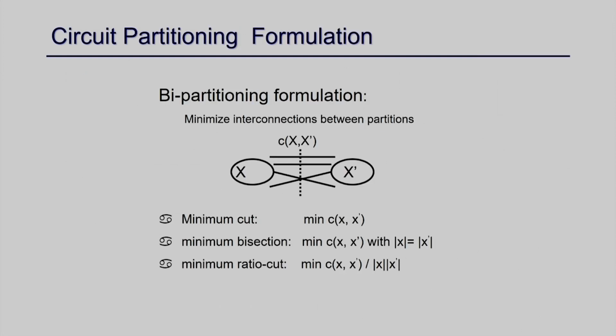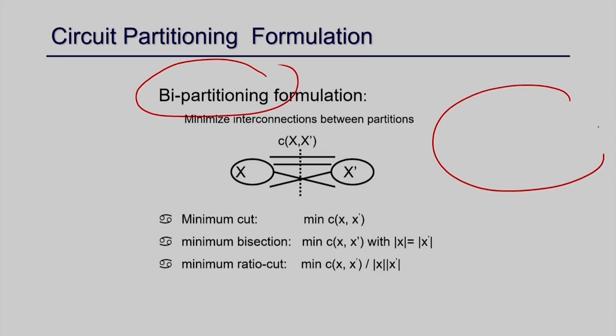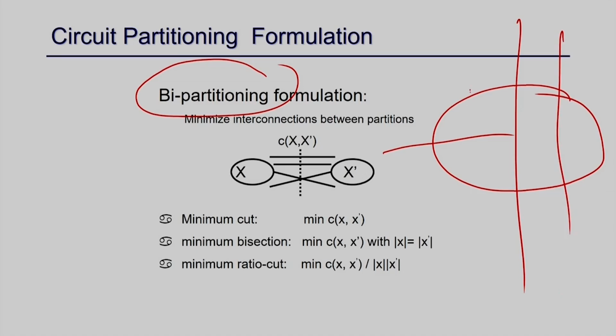Important. If you formulate the circuit partitioning problem, our objective is to try bipartitioning. The partitioning can be anything, right: it can be k-partitioning, where you partition into k components. If it is bipartitioning, you make it two. You can do it recursively: I break the whole circuit into 2, then each of those is again split into 2, and so on. This is what is called bipartitioning, where I partition the whole design recursively, right.